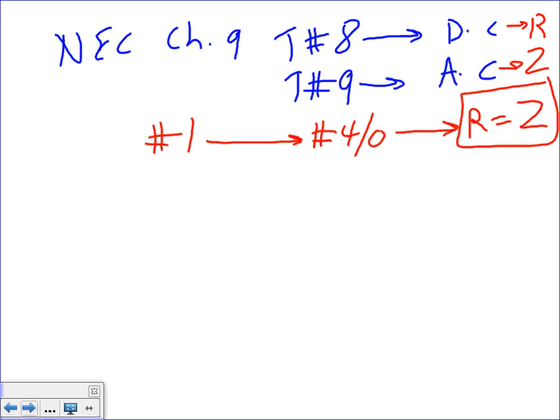Now, what is the capacitance of a cable going through this conduit? Well, there's a hot conductor inside the conduit and a grounded surface, which is the conduit, right underneath it. The two together create the capacitance, believe it or not, and there will be impedance because of leakage of current in between them. That creates impedance. And this is the capacitance.